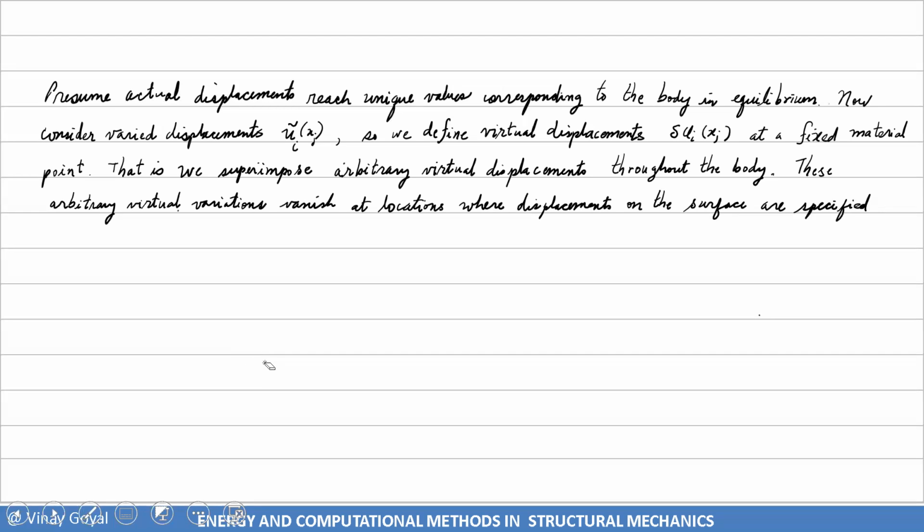if we have a body of material and I apply loads to this body, body force B_i, traction forces T_i, and so forth, and maybe even accelerations, what we're saying is that if this body is in equilibrium, we will consider varied displacements so that at every point which has already deflected an amount u, we consider a varied deflection from that point.